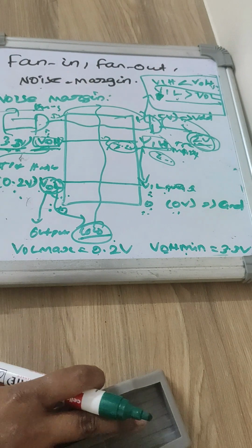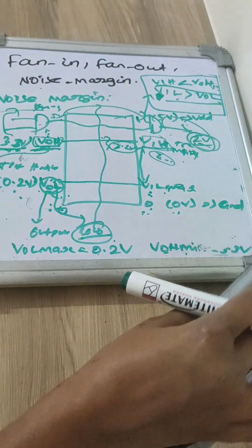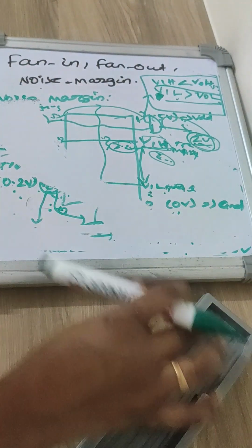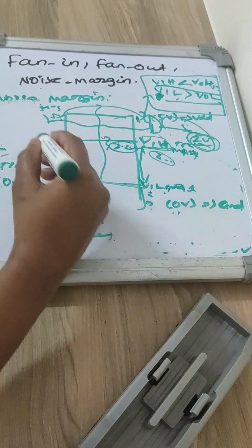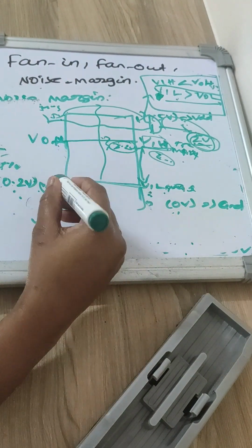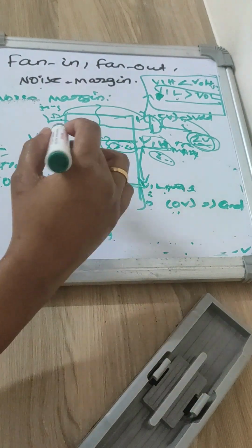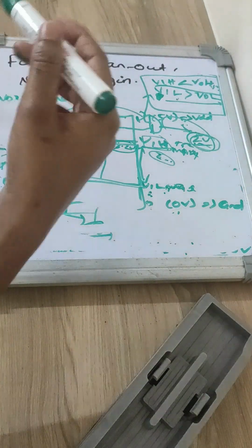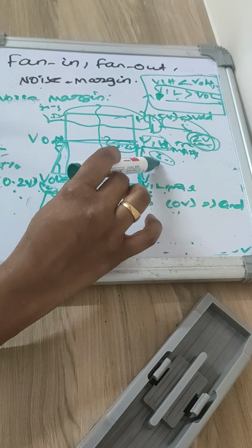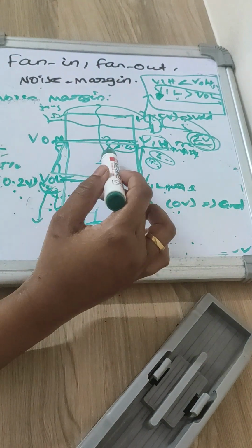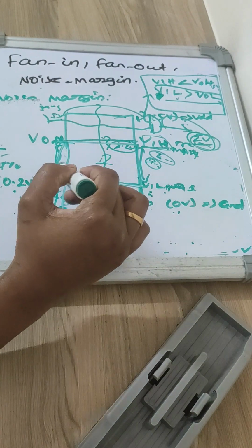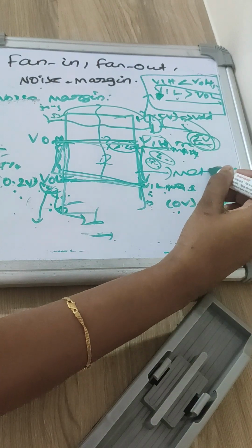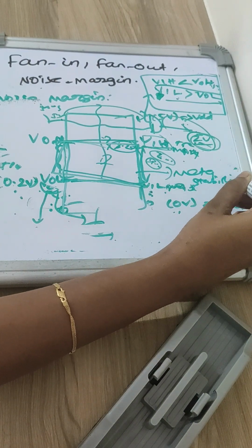Okay, now we are good with all the definitions, right? So here, what is the noise margin? One more thing: here it is VOH, and here it is VOL. Now if any output voltage, or the input which is reaching this gate, because of some gate delays, wire delays and all, falls under this particular range, it will enter into metastability. Okay, it will enter into the metastability.